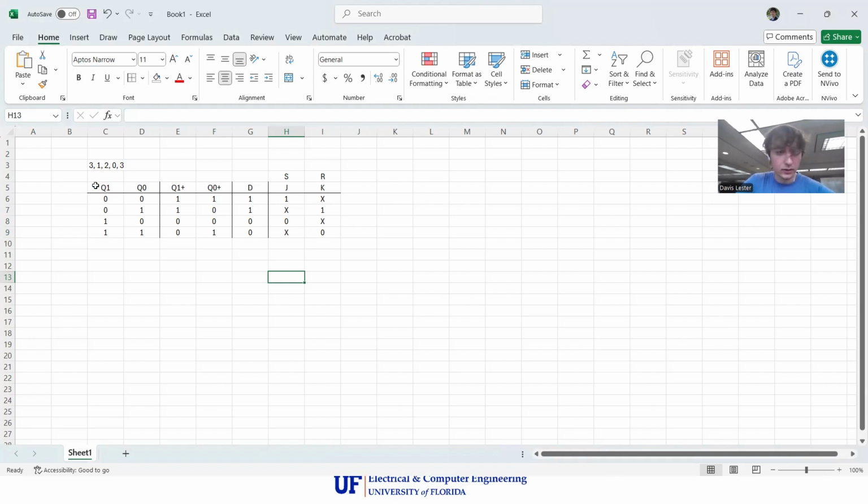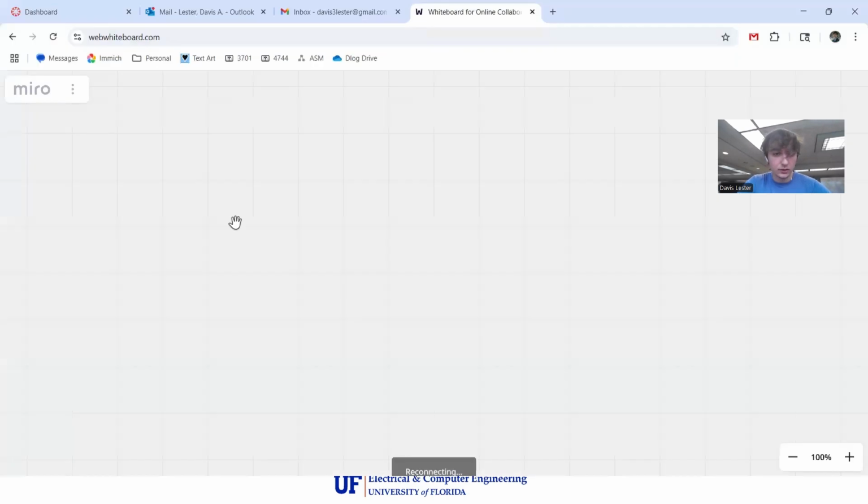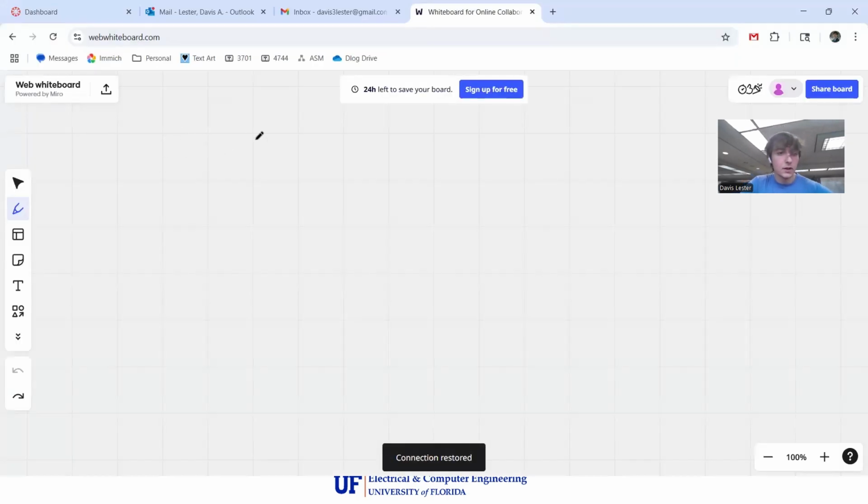So I'm going to look at Q1 and Q0 and determine the equation that's going to generate D0, D. I'm going to swap over to Chrome because I have a nice little whiteboard. I may not be the best with the pen on the computer, I'm using the trackpad, but I'm going to try. So if I have Q1 on the vertical axis and Q0 on the horizontal axis, for my K-map, I can have 0 and 1, and 0 and 1. So I'm going to draw it like this.